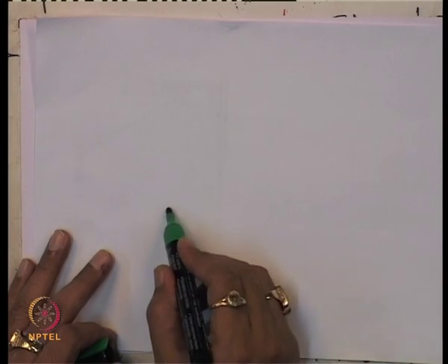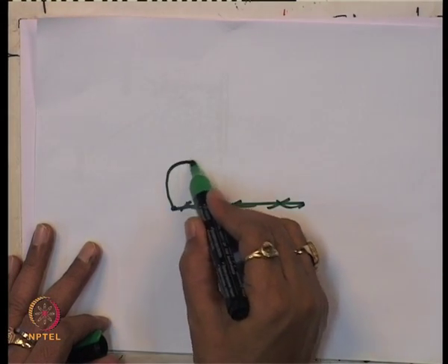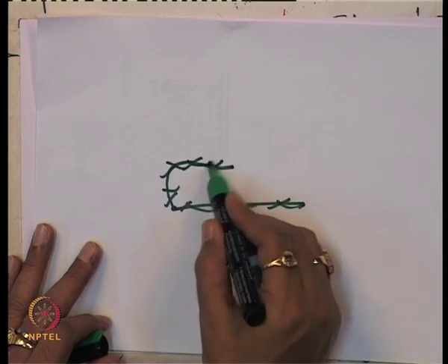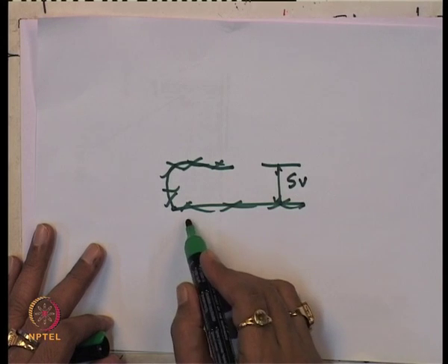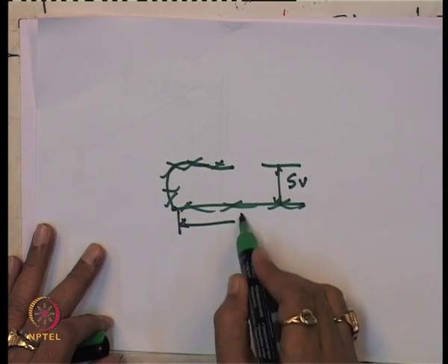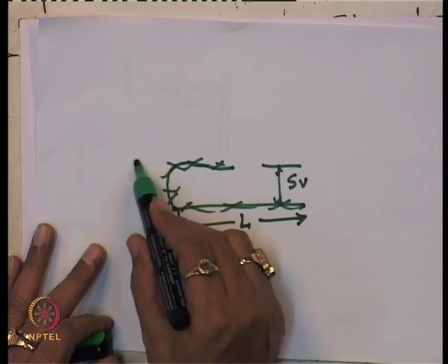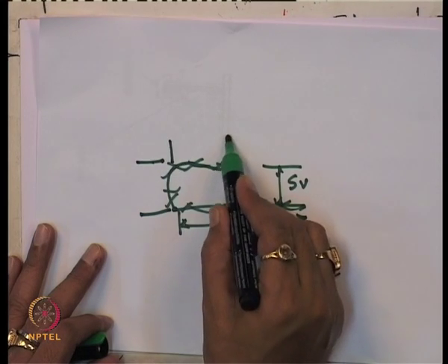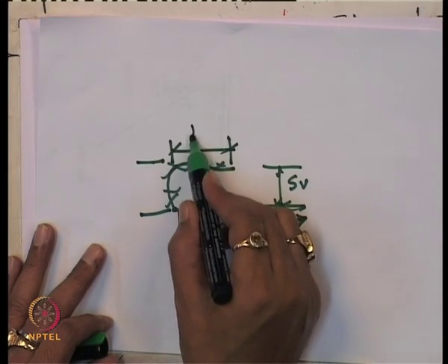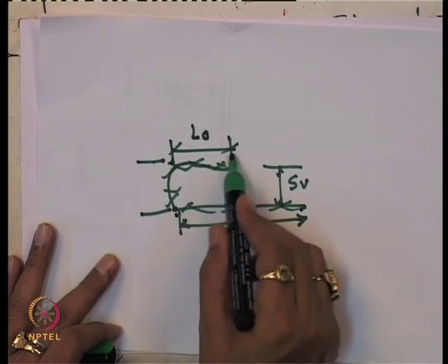If this is the geotextile material and this is the spacing, here the spacing is equal to SB, here is the total length, that means LE plus LR, and here this is the spacing, and here is the overlap length, that is L0. So total will be L plus SB plus L0.